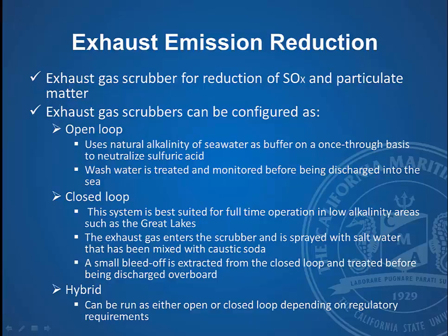and one that's a clean distillate, you can continue to run heavy fuel oil if you switch over to this exhaust gas scrubber. The exhaust gas scrubber removes the SOx and the particulates from the exhaust plume by spraying water into the scrubber, and almost like a shower, that water is atomized.